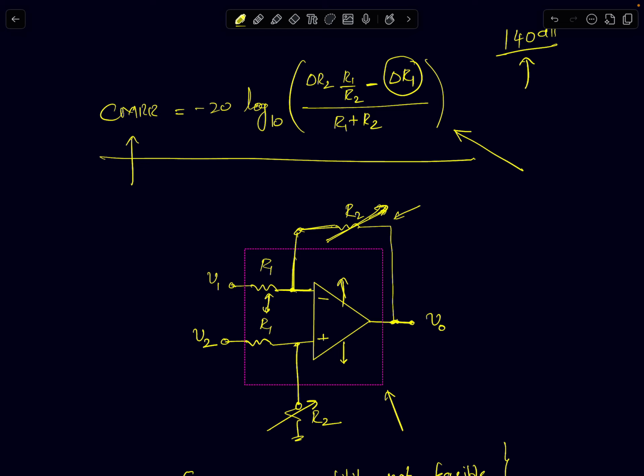Now you give this pin as an external pin to the chip, and you connect a resistor R2. The user, the circuit designer, will be connecting the two external resistors R2 to achieve gain programmability, right? The gain of the circuit is simply R2 by R1. That's the differential gain. I want programmability in this. I can either vary R2 or R1, and whichever you want to vary, you keep as an external resistor, and you give the freedom for the user to vary that.